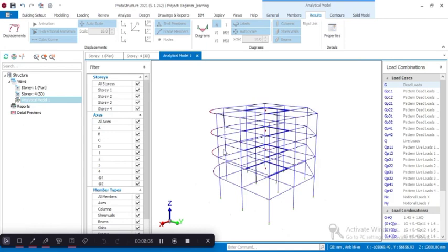If it's not open, you go to the post analysis tab and click display analytical model. So close the building analysis model dialog. The new analytical model tab is set to appear together with the analytical model view. You can go to the quick start guide to get accustomed to the interface.